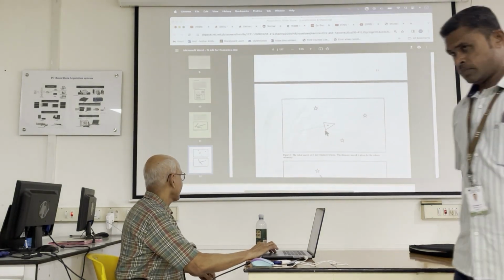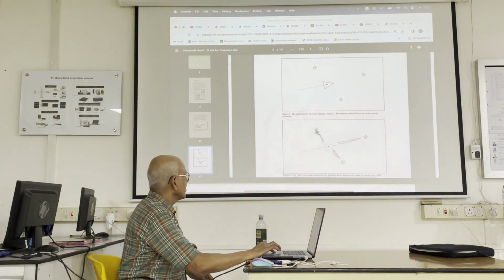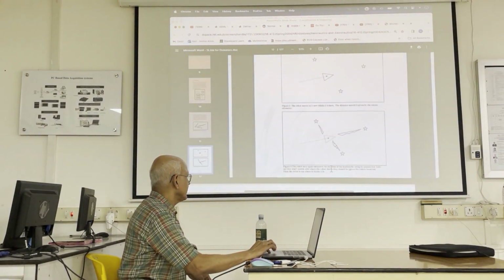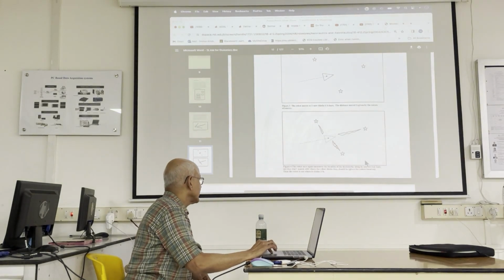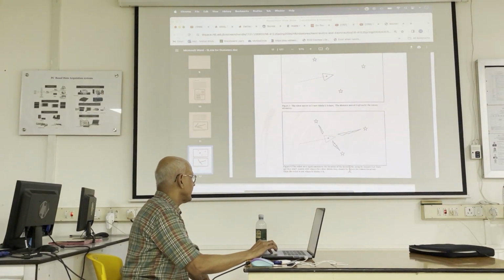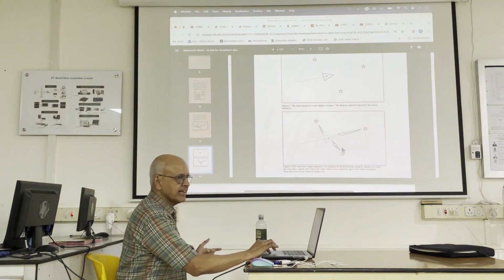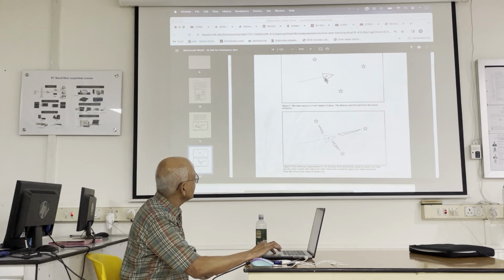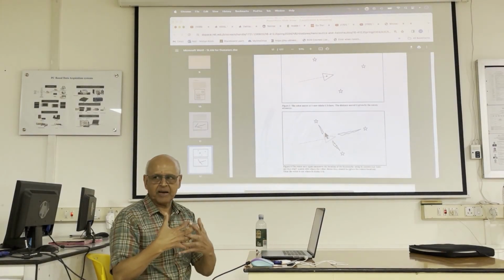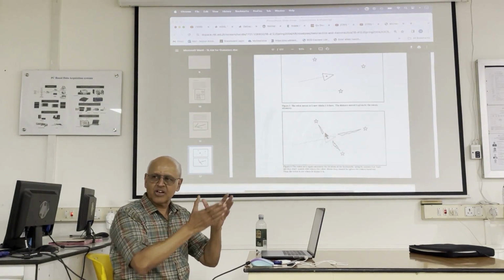Okay, so the robot thinks it is here because of odometry, but we want to correct it. So I take sensor measurements again with the LiDAR, and I can figure out where you are. The robot once again measures the location of the landmarks using its sensors, but finds that they don't match where the robot thinks they should be. Thus the robot is not where it thinks it is. So if you look at the odometry, it won't agree with the sensor readings. If you go with the odometry placement and your sensor readings, there'll be a mismatch. You agree? Yeah. Because the odometry is telling you you're somewhere else.